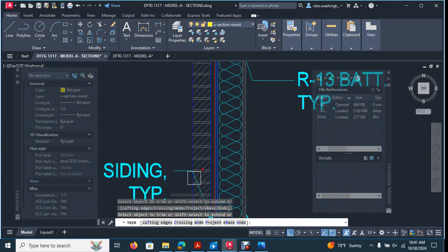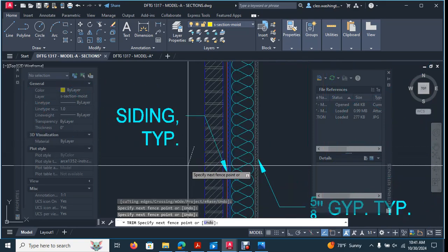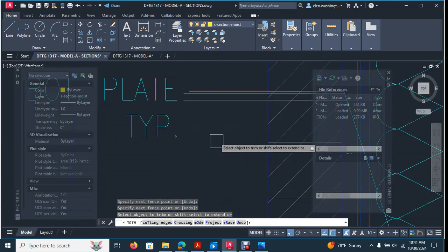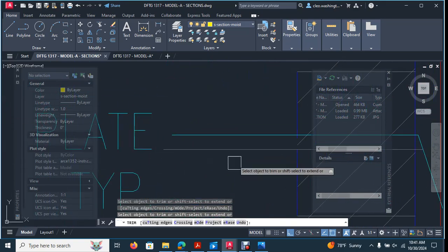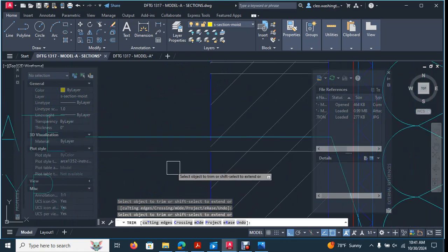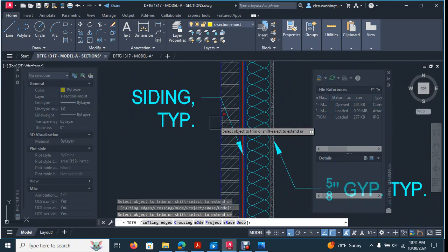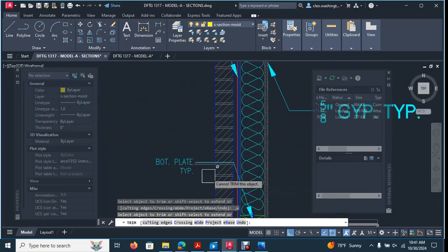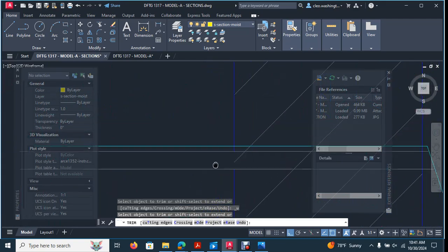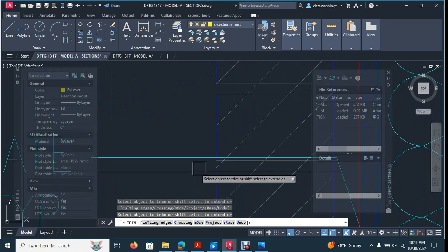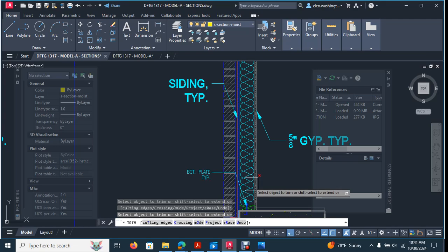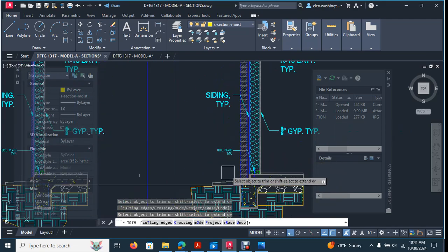Click here and here, and here. And if you trim it and it's not able to see where it's trimming or going to trim it or cut it off at, it'll trim the whole line out. So make sure you're not deleting whole lines. AutoCAD needs to see what you're trimming.